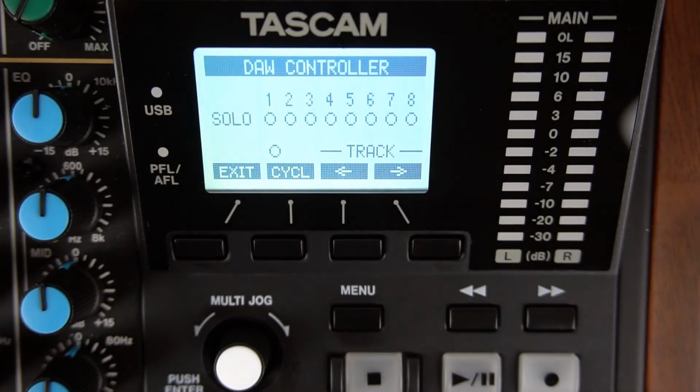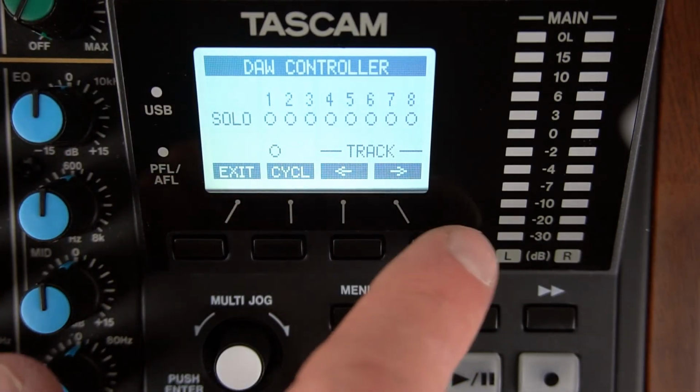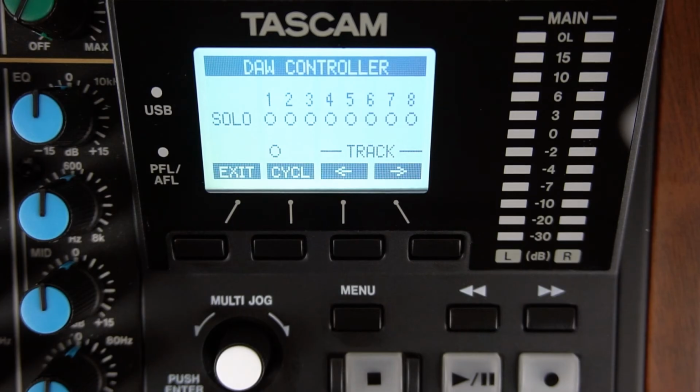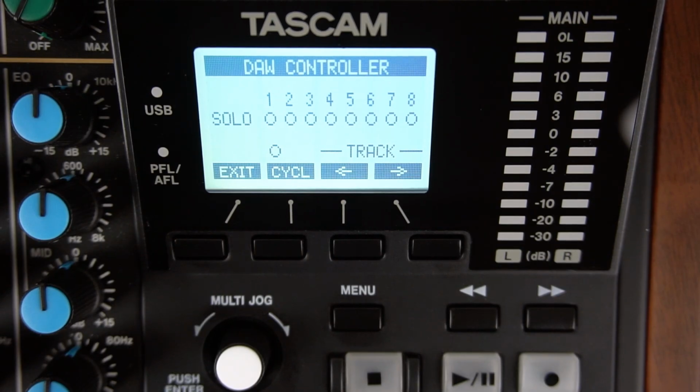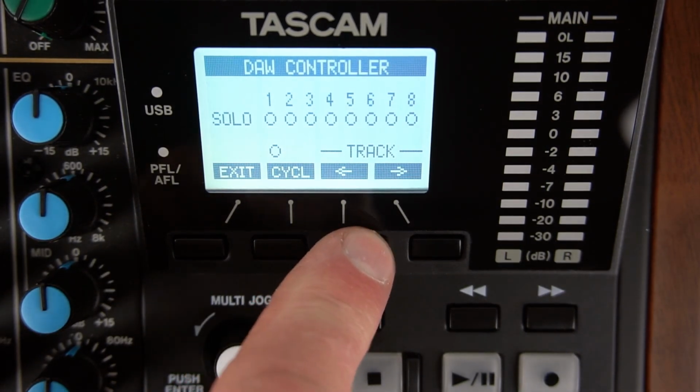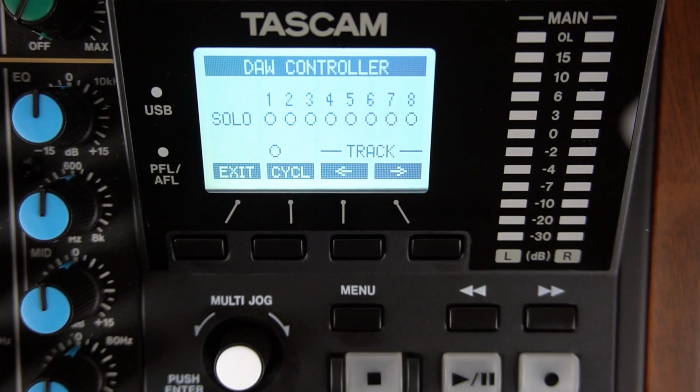The Model 12 will display track. Then press the arrow to the right button under the display, and DAW tracks 9 through 16 are controlled. To control tracks 17 through 24, press the display arrow to the right again underneath the display. Now tracks 17 through 24 are controlled. To go back to tracks 9 through 16, or 1 through 8, press the display button to the left over, and tracks 9 through 16, or 1 through 8 are then controlled.